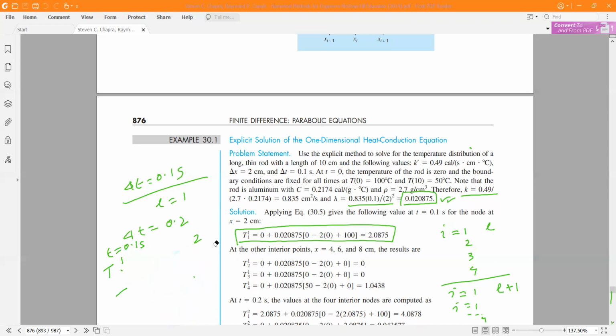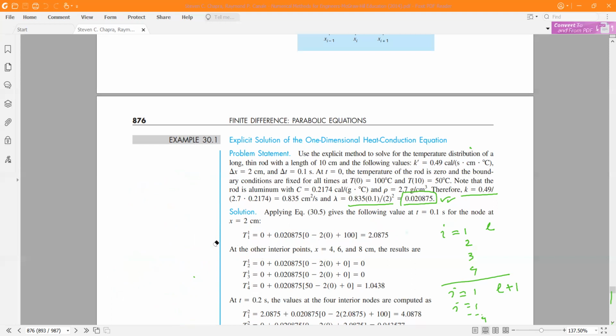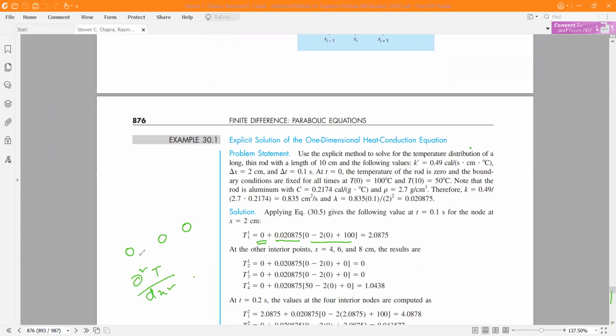If our initial values are there, then we can calculate the temperature at the next time by using the equation already derived. So you can easily see what is happening there. This is your earlier initial value. This is the value of lambda, and 3 nodes are involved. We start from the left-hand side with node 0, then another node, and another node, because in calculating D2T, dx2, you need 3 node points. This is your 0 node point, this is your 1, this is your 2.